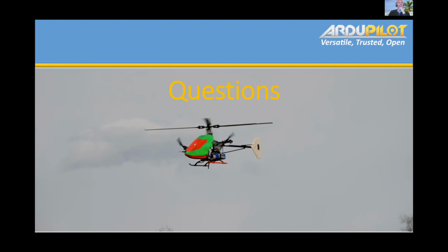One of it is perhaps there's a little corner there where with just multi-rotor acro that we should be supporting better and would actually enhance multi-rotor as well. And that's where the whole spool logic came in. We needed to support heli better. There were some states during startup that were ignored in multi-rotor because we had this instantaneous startup. But for helis, it's really important.